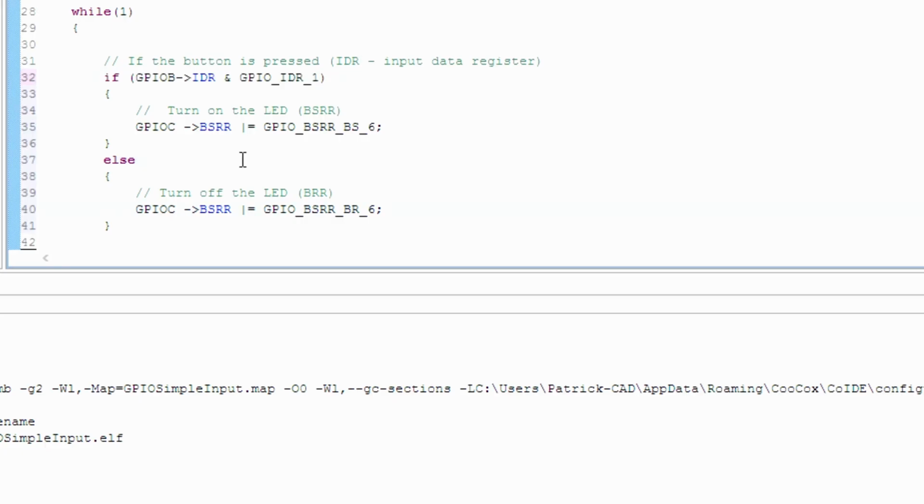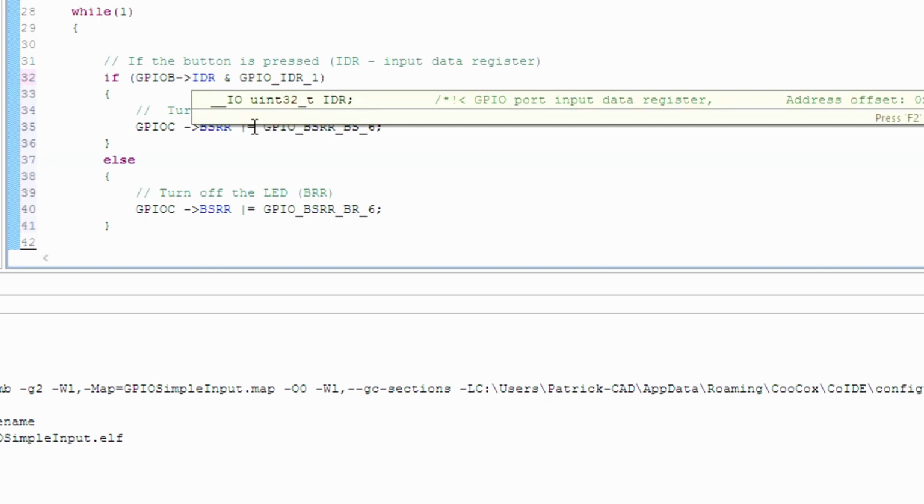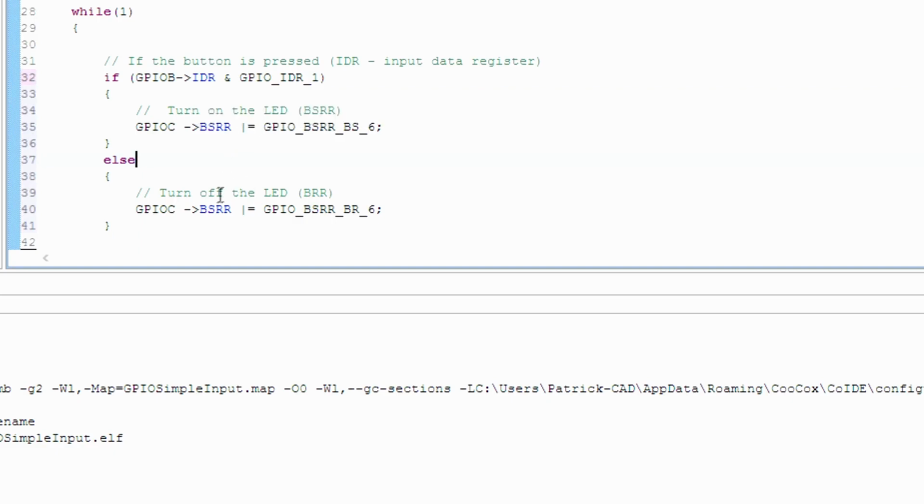Of course, in this simple implementation of code for pressing the button, we're not taking advantage of any debouncing or anything like that, because it's just going to turn on when we're pressing it and holding it down. It'll stay on, and it should turn off when we release it. So it's a very simple implementation of using the button. We'll take a look at more complex situations where we're debouncing and when we're using interrupts to turn it on and off. So let's see if this works.